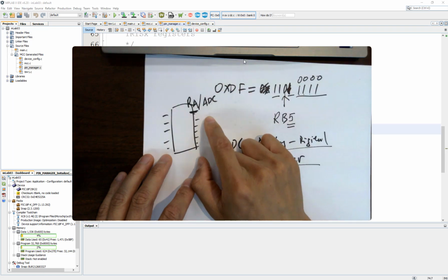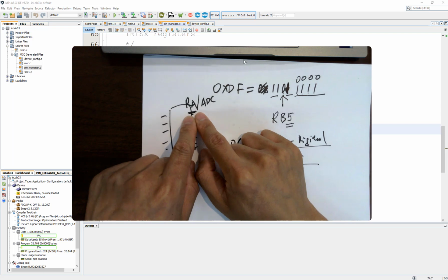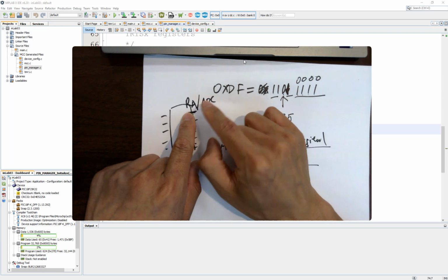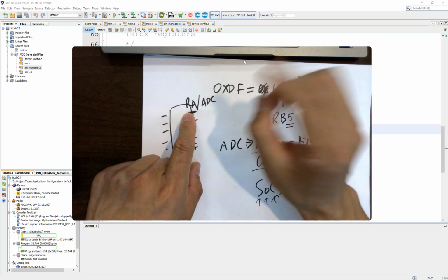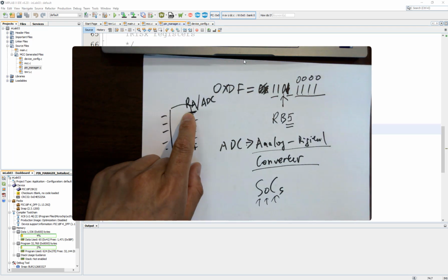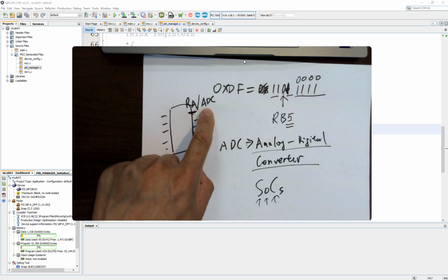However, for other purposes, you just want to multiplex it because some of the pins, like the A ports, are used as general purpose IOs, GPIO, to toggle on and off certain LEDs or output a certain protocol. You can definitely do it. But sometimes they are also used as ADCs.